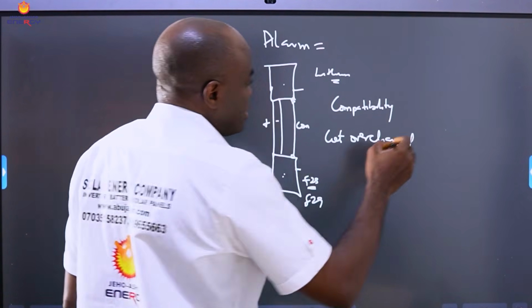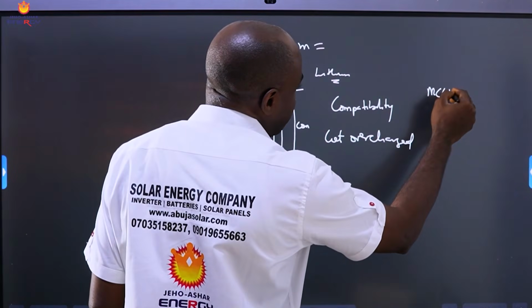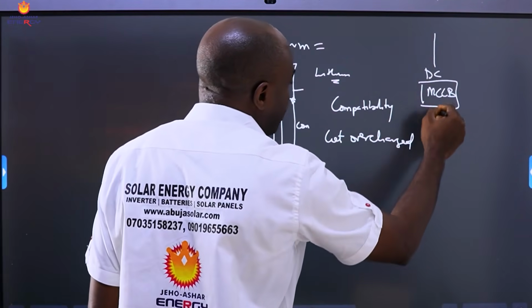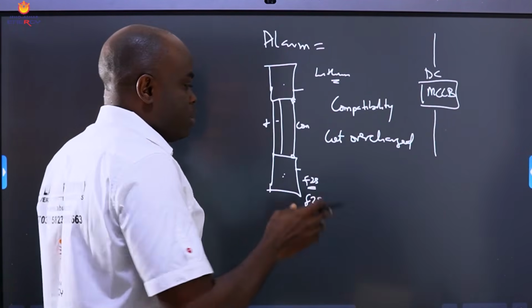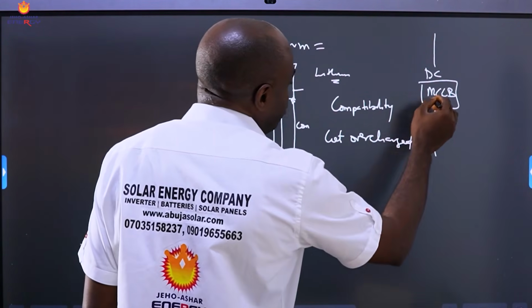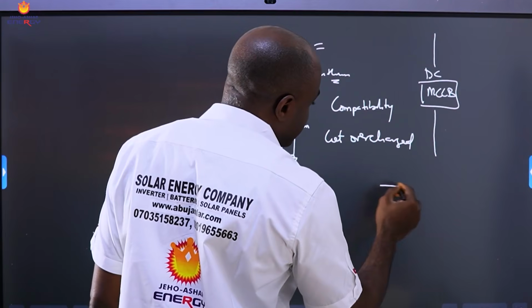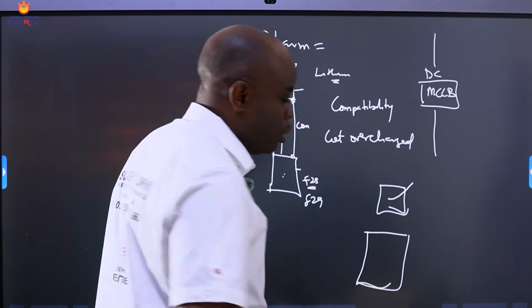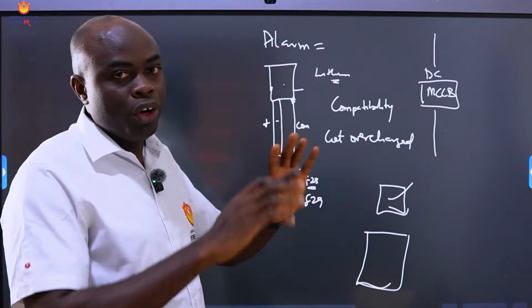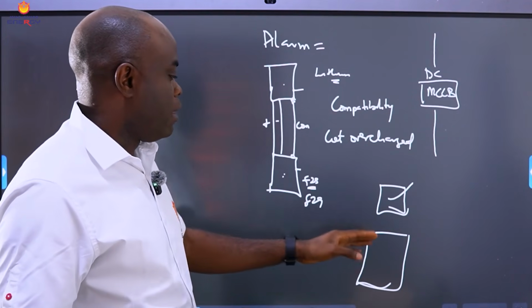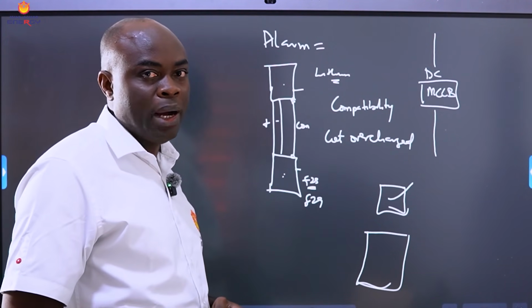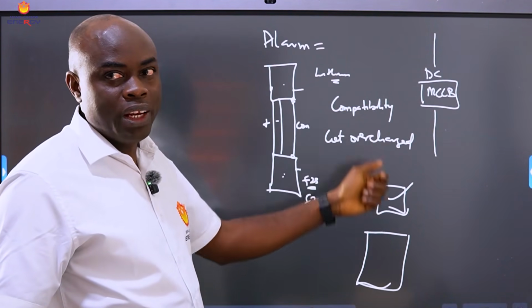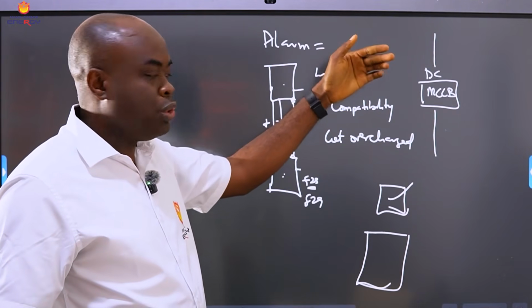Another aspect again is your protective device. We call it MCCB DC between your inverter and your battery. Most of the time, with these batteries, you don't put power on the breakers when the battery is on. Okay, you want to power on your inverter from scratch, right? What you do, you turn on your battery. When it comes up, you take up the breaker. When the battery breaker goes up, then you turn on your inverter.